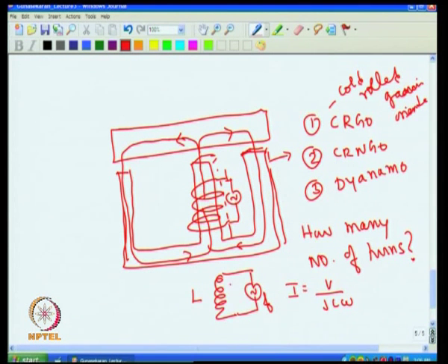Then there will be a current flowing through this that produces a magnetic field. That means, if I connect this, the current flows through it and produces a magnetic field, and that magnetic field goes through the core, and it is multiplied by mu r. So, if I put a very low L, that is a small number of turns, you will get a very low value of L, and then there will be too much current, and too much magnetic field will be generated and flow through the core. This core has one problem: if you increase the current, the magnetic field will increase.